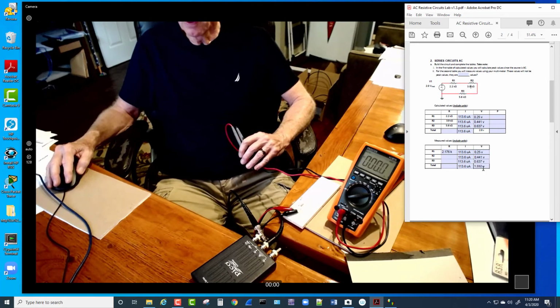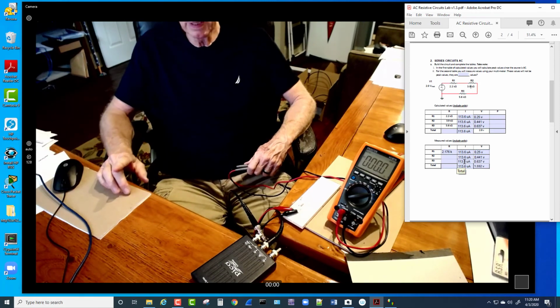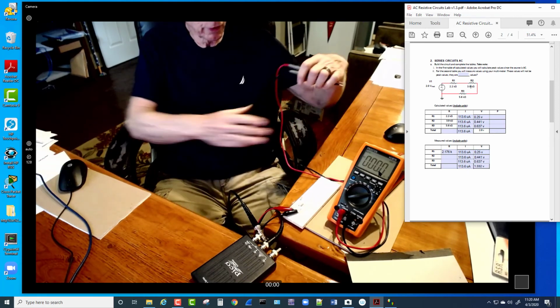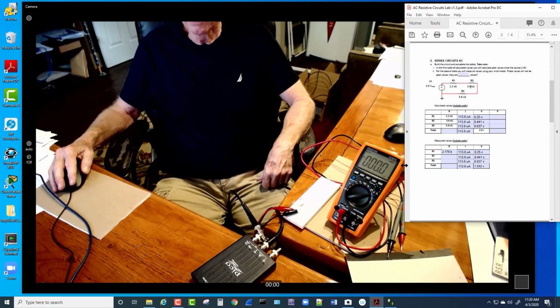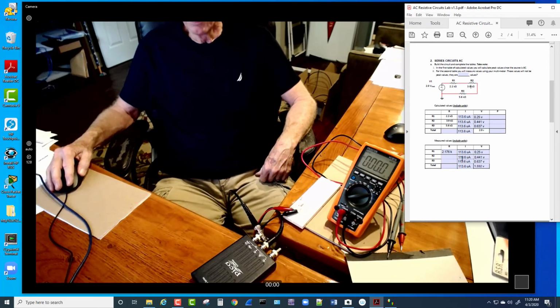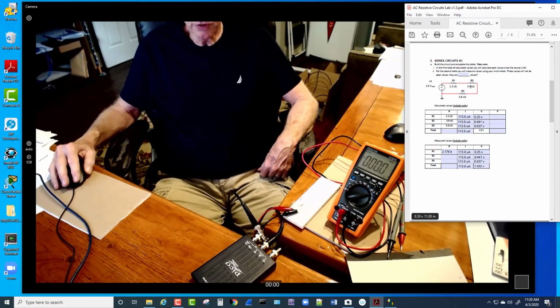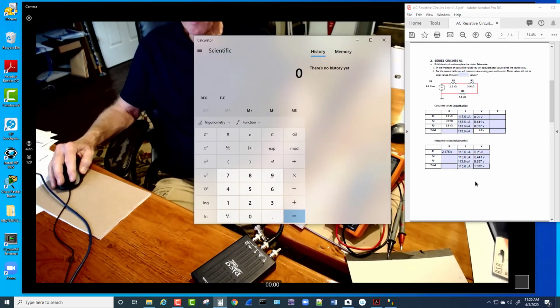So why didn't this match up to that? The reason is because the multimeter is measuring RMS, not peak. And when we had that initial discussion, oh, I owe you those PowerPoints, so I'll put that together too and send it. The relationship between this RMS value, which we're going to explore in the next video, and the peak value is 7/10.